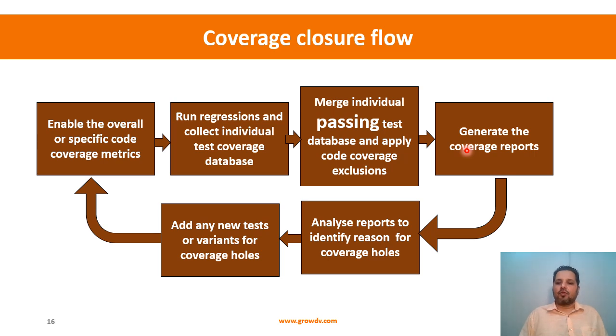Ultimately you might add a few exclusions after discussing with the entire team, and once you have the common consensus or the agreement, you add those exclusions and you write reasons for those exclusions. That is very important, because just adding an exclusion is not sufficient. You have to capture why we have added that particular exclusion, and then your coverage becomes 100%. So you say that now from the coverage metric point of view we are signing off on the design.